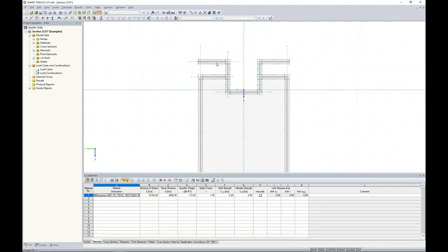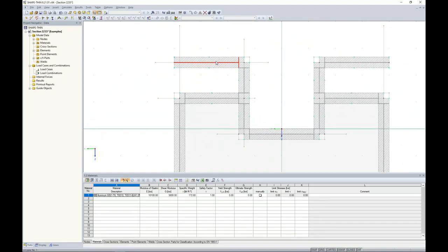Now, you'll see these symbols at each element, and this is the width to thickness symbols, those C over T parts. So this is what's recognizing width to thickness, but even more so, you'll notice that at these closed ends, we have what looks like a T symbol, but at the open ends, we don't have that same symbol. So this, again, is important for aluminum design to tell the program how the edges are supported. And over on the right hand side, we can see that it's supported, but over on the left hand side, it's not supported. Again, important for local buckling.